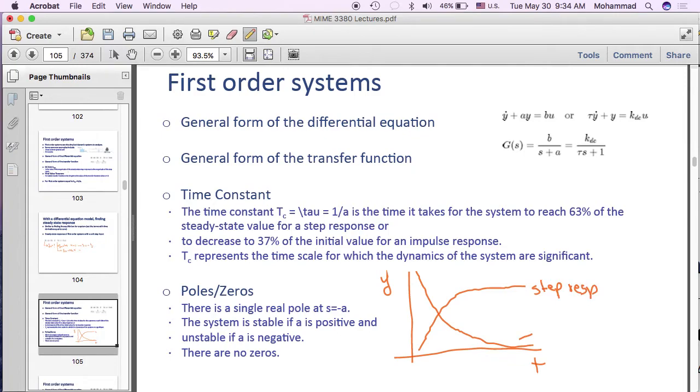And this is what is called an impulse response. And the reason we call this an impulse response is an impulse is a large input that happens over a very short period of time. Now keep that in mind and imagine a tank. If it is a reasonably small tank, an impulse response would be taking a bucket of water and dumping it in the tank at time 0.